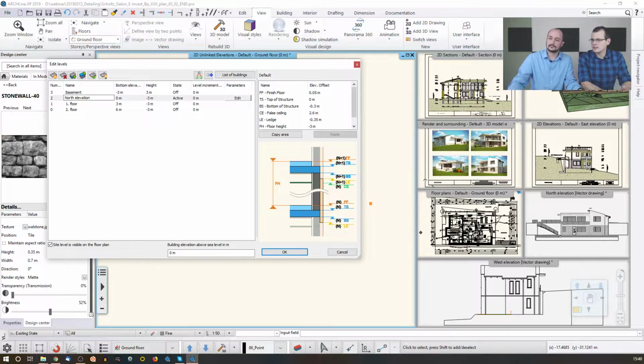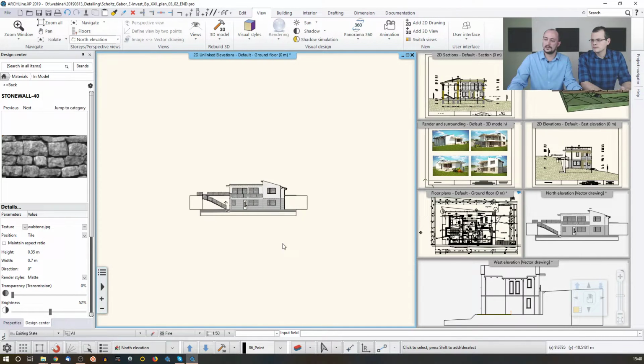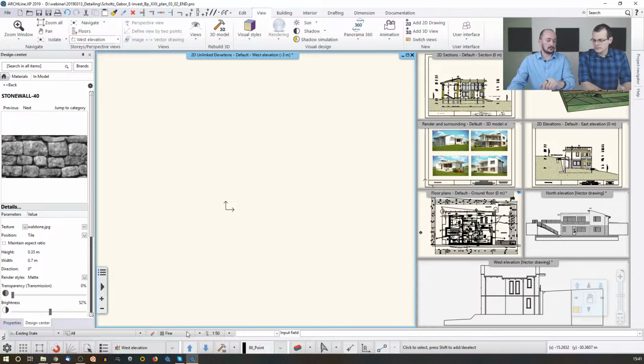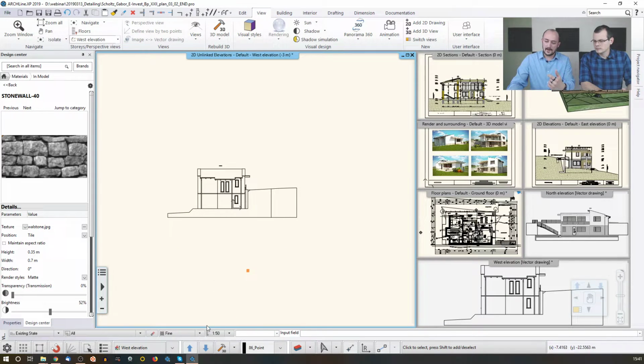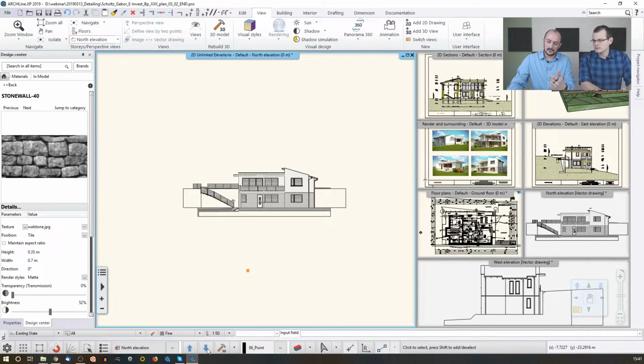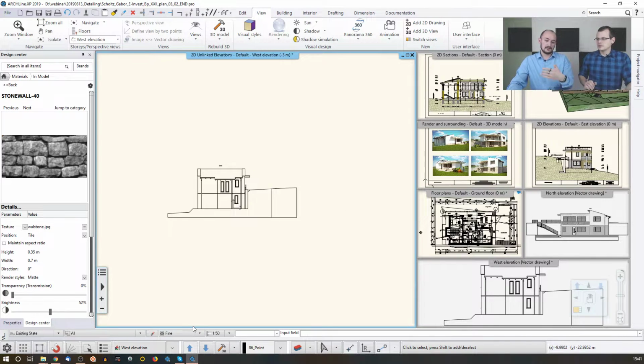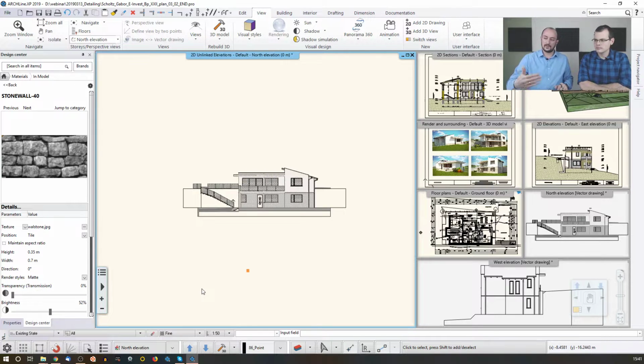Elevation. It was west, I think. And let's just name this as west elevation. Okay, I'm fine with that. Let's just say okay. And then I just jump to the west elevation. I'm just using the page up, page down button, which we covered previously. So I just paste it here, and then I have that over there. So now when I flip and change between the pages, the levels, these are now handled as pages, and I can just do whatever I want with those.